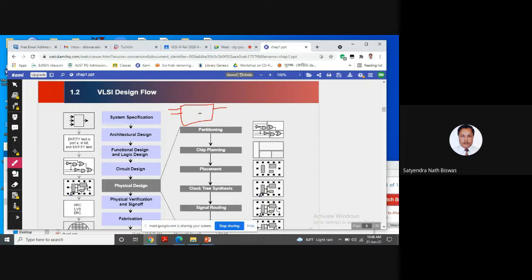In some complicated adder circuits, you need two outputs because there will be a carry. Also, if you use the full adder in the first place, then you have only two inputs. But if you put it into an intermediate stage, then there will be another extra input, which comes from the carry of the previous block. So this is the complete specification of a full adder. That is called system specification, and these are the things you need to know from it.